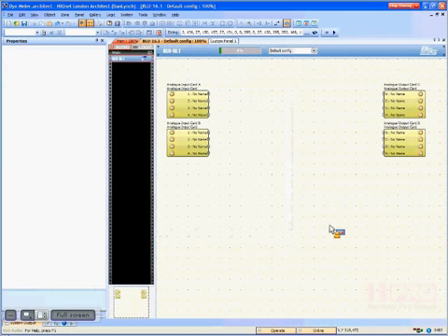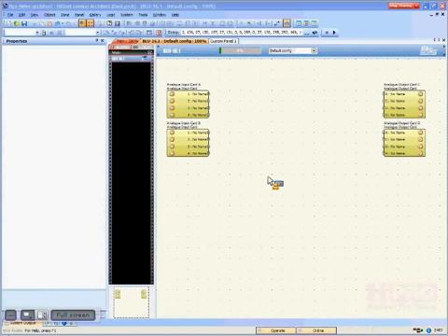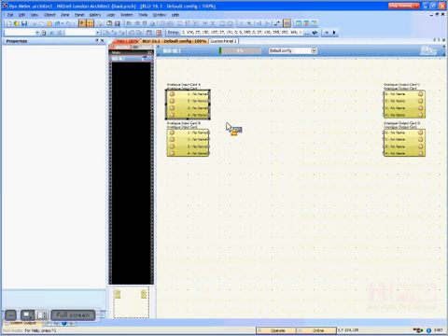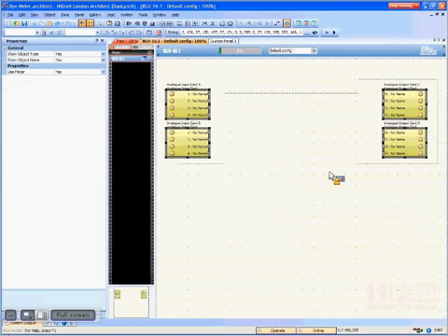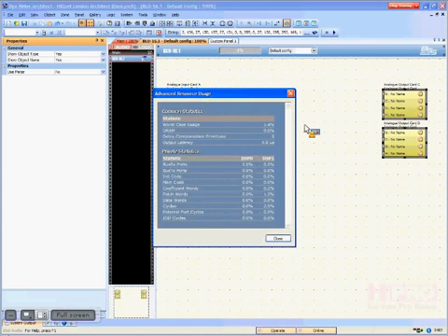Where's the rest of our DSP power going? Where's that 4.4% going? What the heck's it being used for? Any guesses? Input cards and output cards all have meters on them. Somebody's got to control those meters. In this case, it's the Shark chip. Turn those meters off, drop down to 1.4%. What's sucking up that last 1.4%?